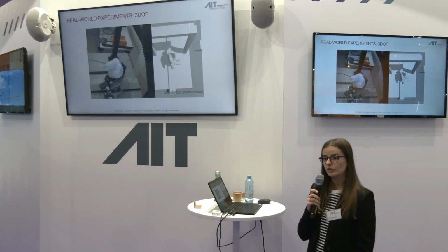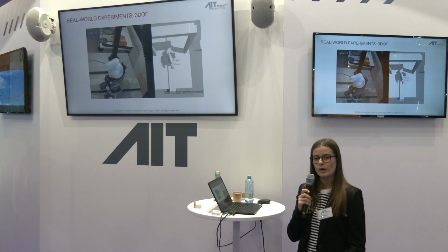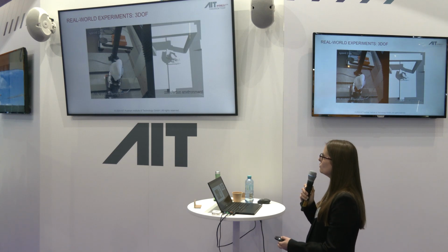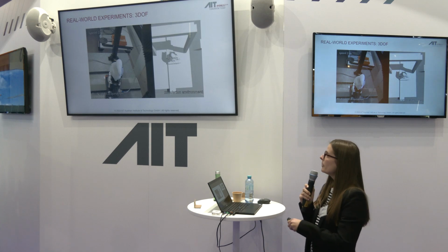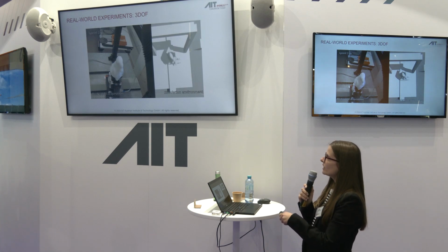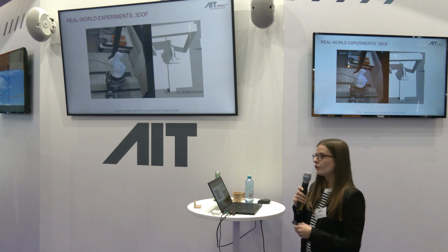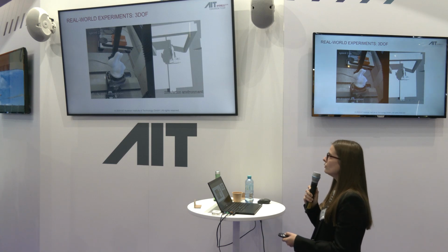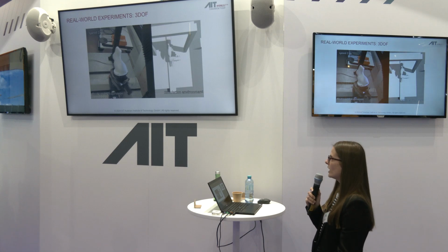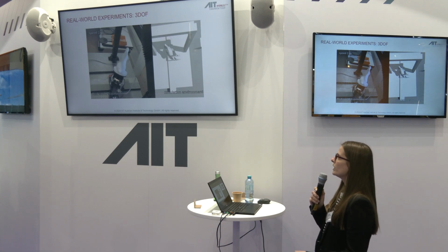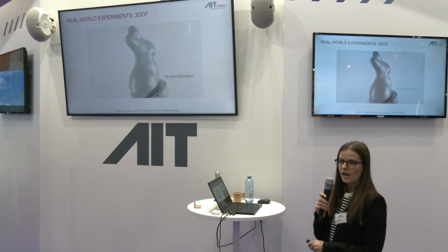We also had a digital twin in which we were able to evaluate how the object was going to move. And the object moves on the setup so that the camera can acquire point clouds from different views. And then these views are stitched together, for example, with global ICP or generalized ICP, in order, for example, to reconstruct a 3D model.